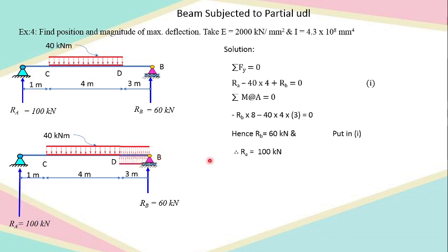So here you can see I have added UDL in the downward direction, right? As I have added it, I have to subtract also. So ultimately the result of these two UDLs newly imposed will be 0. Plus 40 kilonewton per meter downward and 40 kilonewton per meter upward is going to nullify the effect. So due to this addition of UDL for the span DB and subtraction of the same magnitude of UDL on DB, it is not going to disturb the originality of this problem.